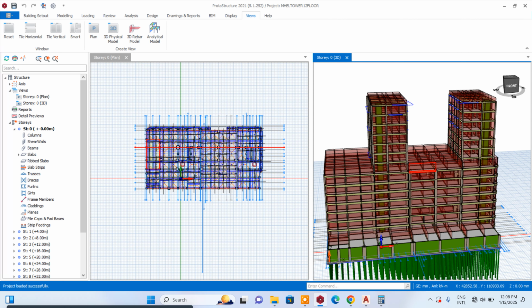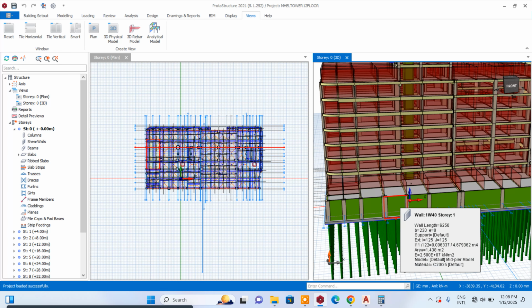Now, there are some designs that are so complex that it takes time to design, model, and analyze them, and you ensure that all members have passed before you go into your foundation. For the design we have here, we tried to design just on the type of foundation that was proposed from the soil, that was piles. When we were about to carry out this design, we discovered that we were having a lot of piles.